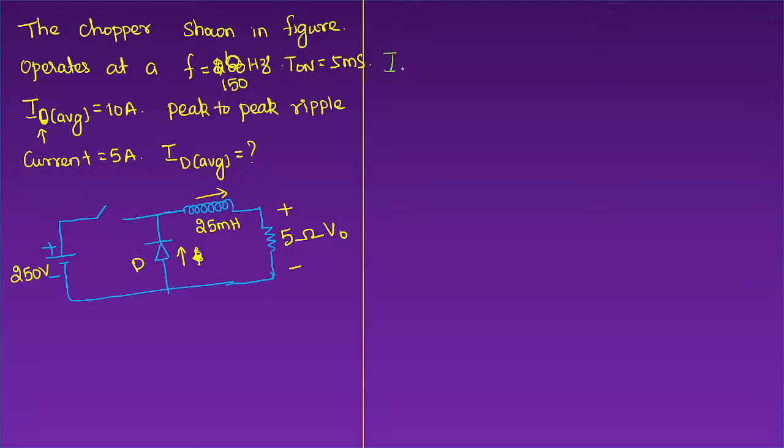Calculate. Take first the freewheeling diode. Find the average current flowing through the freewheeling diode. Then find the RMS current flowing through the freewheeling diode. Then take the switch, calculate the average value of the switch current, and again calculate the RMS value of the switch current. Do it slowly and properly, I am not asking you to do it in a hurry. Then calculate the output power. Estimate all these parameters and drop your answer in our Telegram group.